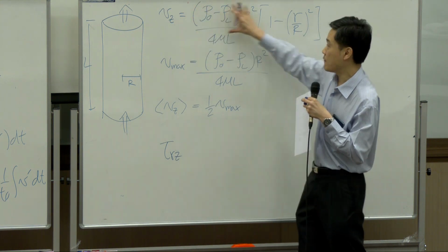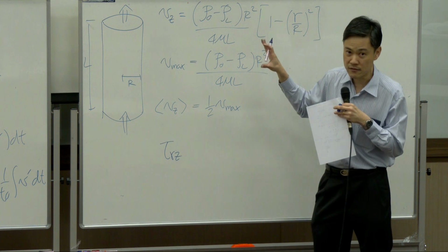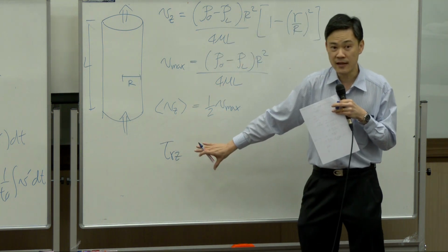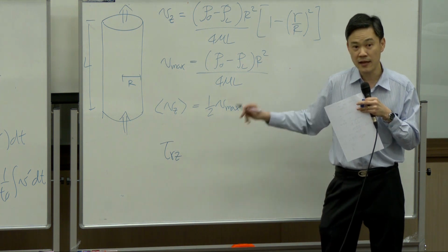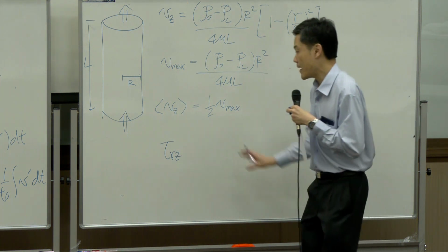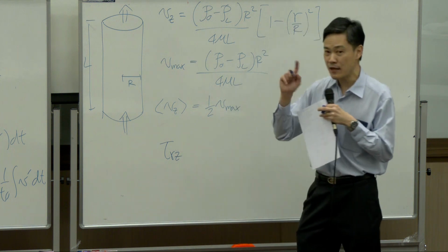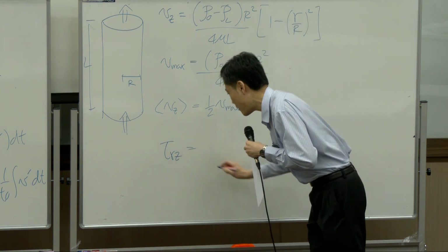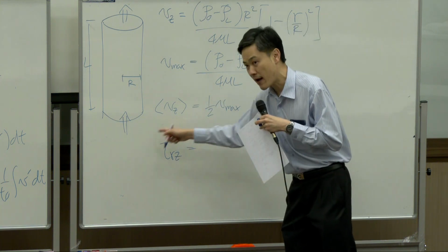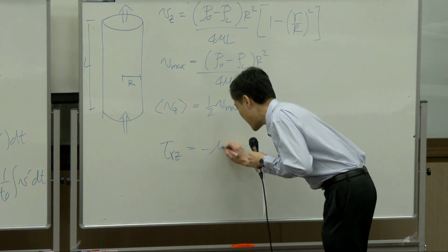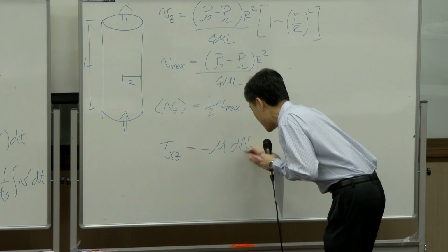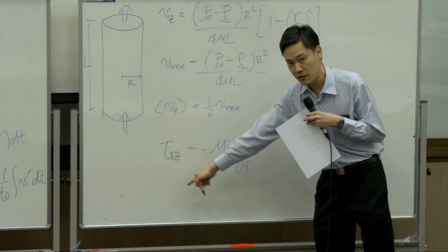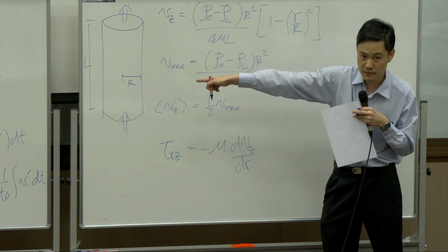So if the velocity profile is given, then in order to get shear stress, it's basically differentiation. It's in reverse. Okay? According to Newton's law, as I said, Newton's law is the only equation that links tau, that is what is transferring, with respect to velocity, which is what can be measured. Okay? This is Newton's law for this particular case.